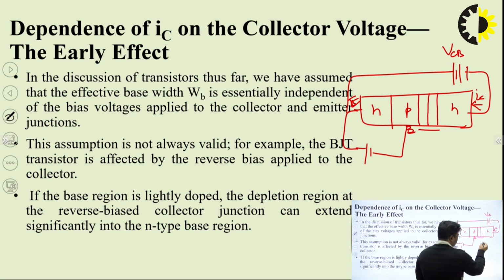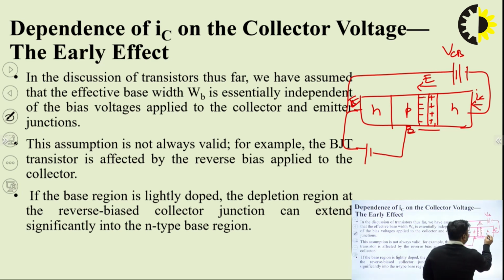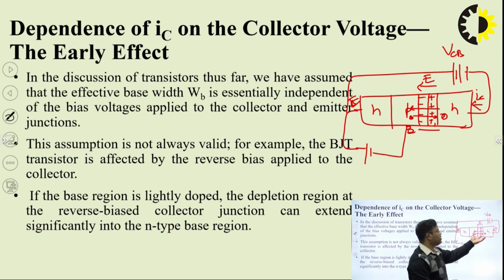But in a reverse bias condition, a space charge region exists across this PN junction diode, and an electric field is obtained. Because of this electric field, a drift of minority carriers takes place, meaning holes on the N side and electrons on the P side will also drift through the junction.